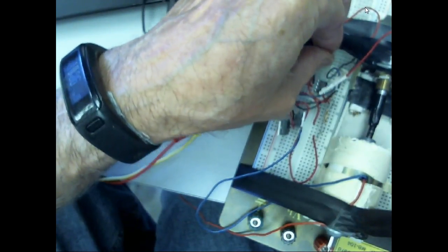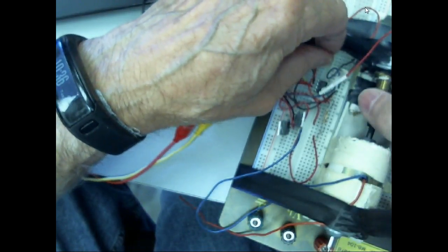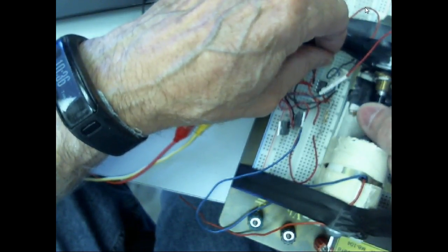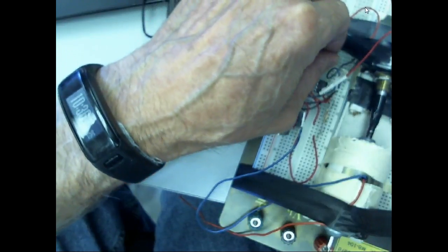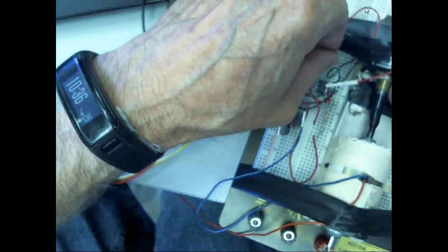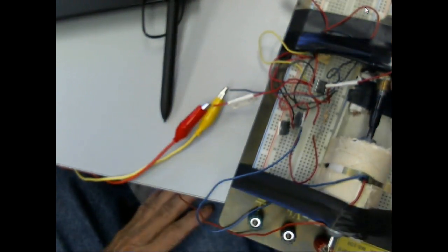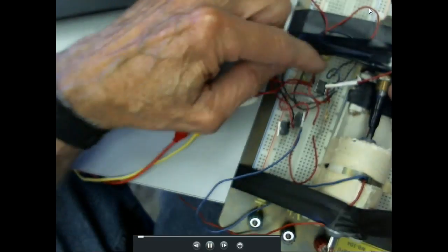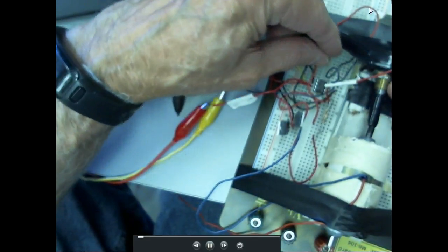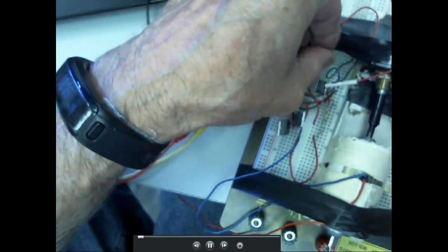You see what's happening? Now it's oscillating because it's proportional control. We can probably make it stop if we slow it. And plus it's using tape as a coupling. So as soon as I get an error in my error amplifier, it decides which direction it needs to turn the motor. And it turns the motor until the output of this pot matches what? The output of that pot. So this is a closed loop system, guys, using a pot as position control.